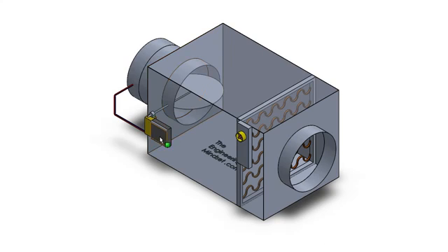So we've got the controller located here, mounted onto the actuator. The actuator controls and rotates this shaft, and connected to the shaft is this damper. The damper can modulate its position to control the flow and the amount of air entering into the box and thus entering into the zone.